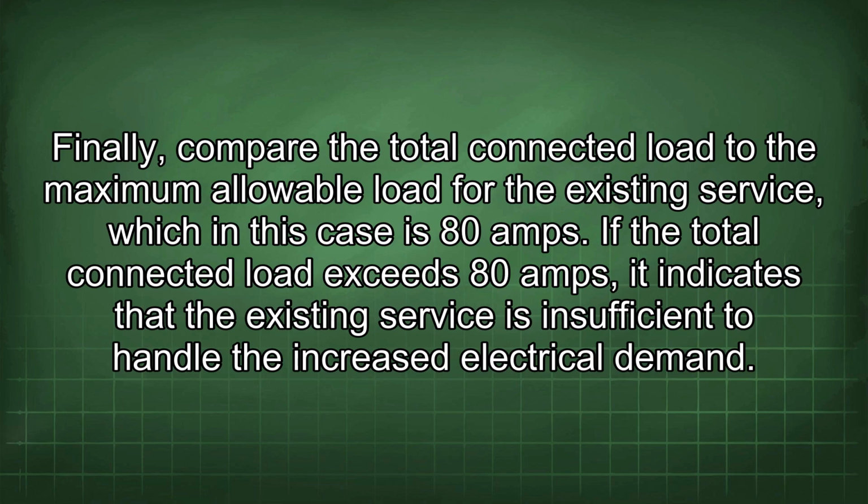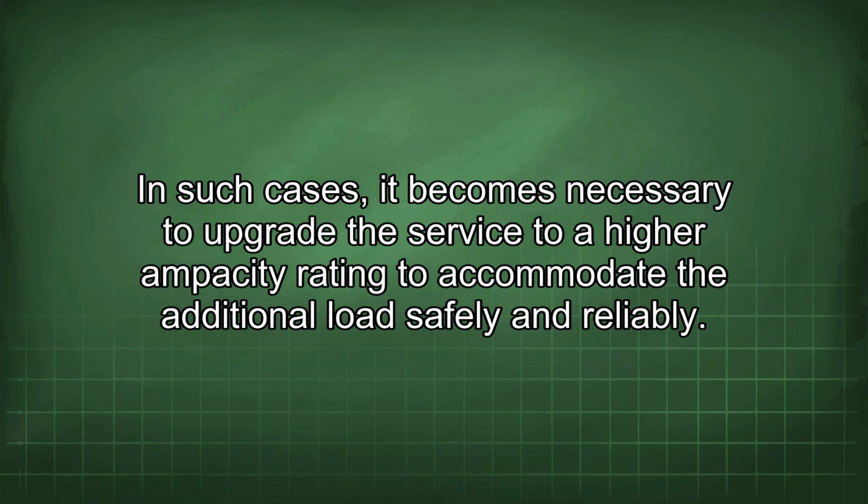Finally, compare the total connected load to the maximum allowable load for the existing service, which in this case is 80 amps. If the total connected load exceeds 80 amps, it indicates that the existing service is insufficient to handle the increased electrical demand. In such cases, it becomes necessary to upgrade the service to a higher ampacity rating to accommodate the additional load safely and reliably.